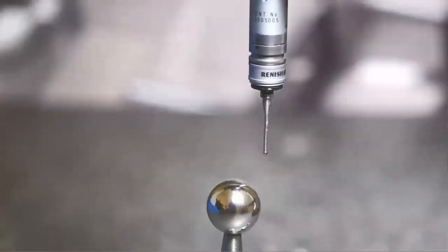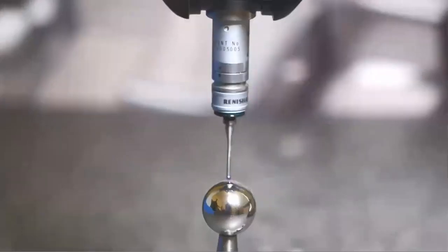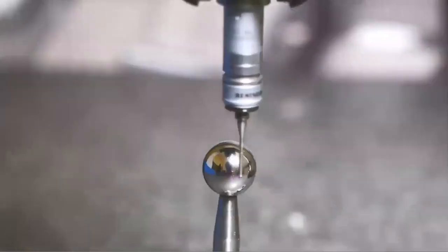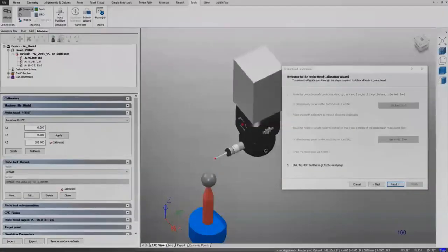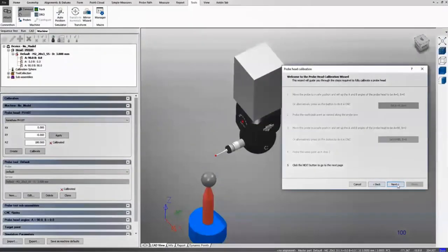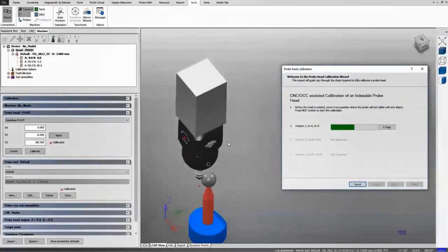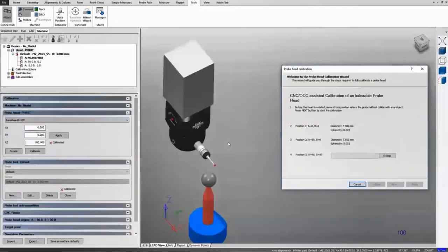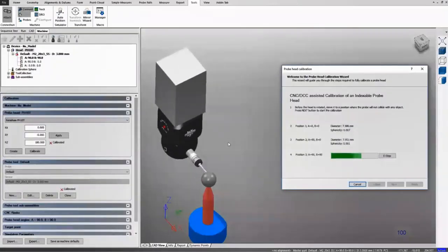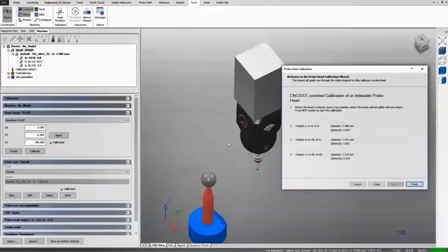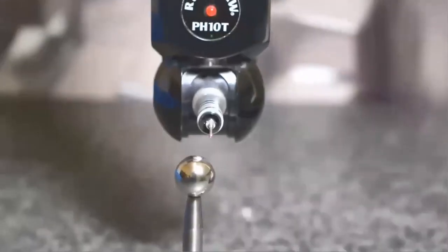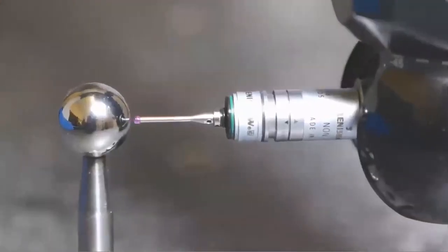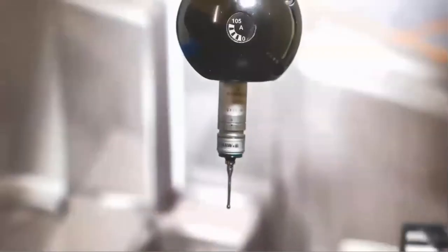Probe calibration on CMMs and manual devices as well as machine tools can be done in a multitude of different ways. This can be done from within PowerInspect or directly in the protocol if doing calibration independently. This is usually the case when using the I++ protocol on CMMs. Calibration for CMMs in PowerInspect is done using the simple probe calibration wizard. This process ensures all necessary probe angles are calibrated before the inspection is carried out.